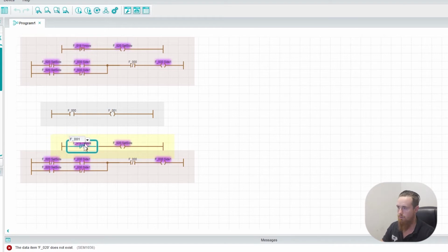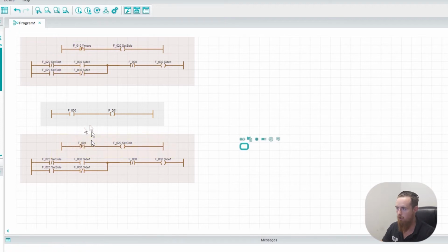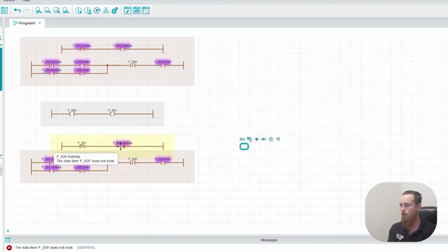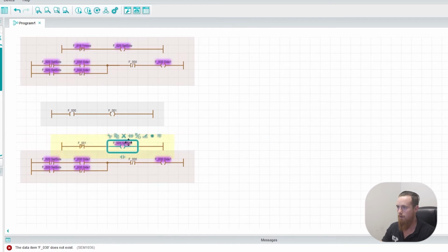So notice the reason why I've done this in 2 different PLC programs is it's a little bit different. The programming language is both kind of ladder logic. This is a little bit more function block diagram type of programming. So there's certain things that you can get away with and do a little bit differently in this logic versus the other type of logic. That's something to keep in mind as you program on different PLCs. There are some things that are finicky and operate a little bit different between PLC programs. So you might have timers and stuff that react differently, just things along those lines. A lot of the built-in features act different.